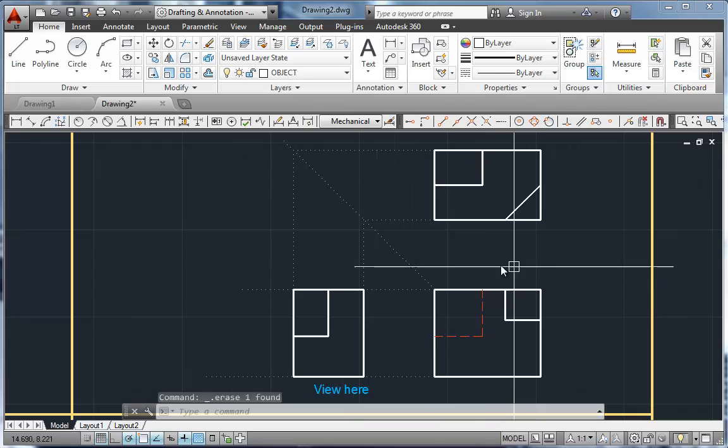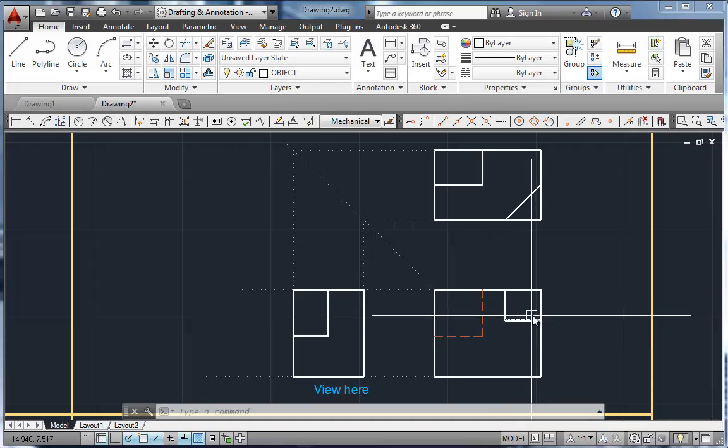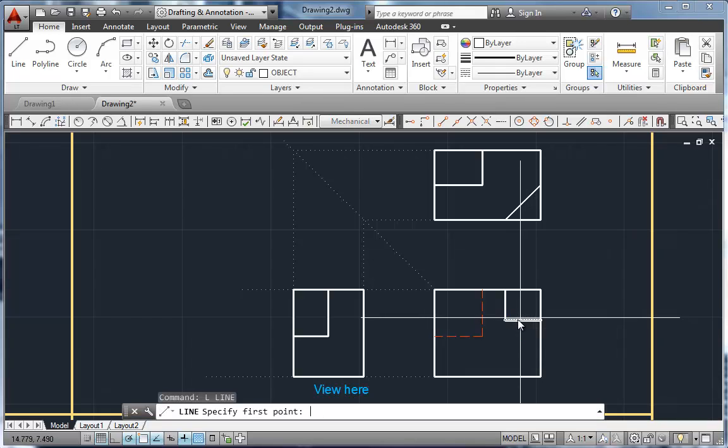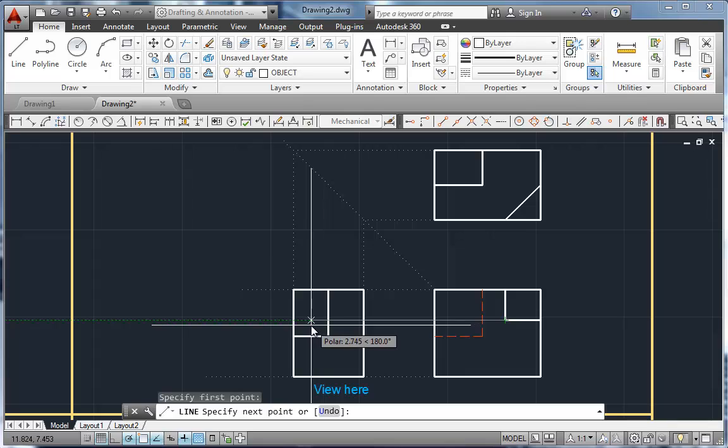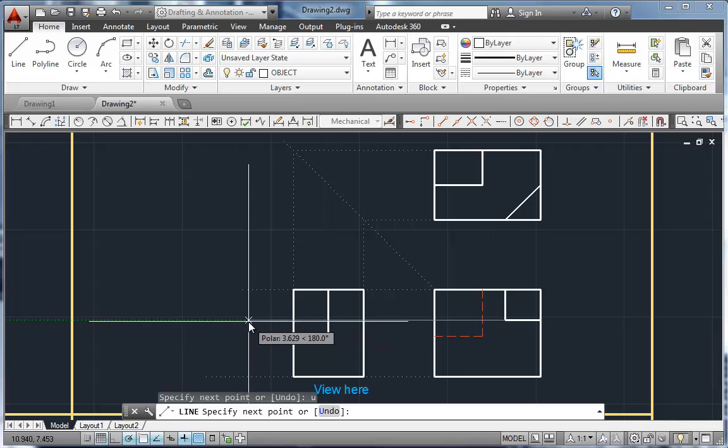Now, back here, I have something happening. I have two lines here that tells me there's a change in this face. And when I look at my top view, I see I have an angled line here that is the same width as this. Again, because this is an object line, and because of the size and shape I see here, the presumption is that this is a cut corner off the part. The corner's been machined away on this angle down to this depth. So I'm going to take the depth or height over. I'll just take it all the way across.